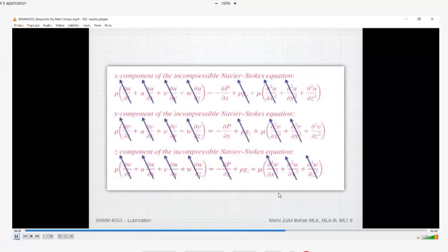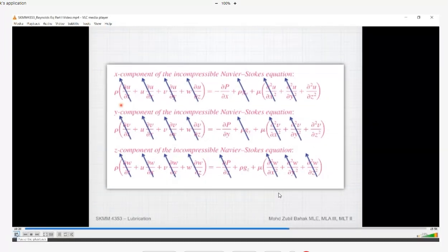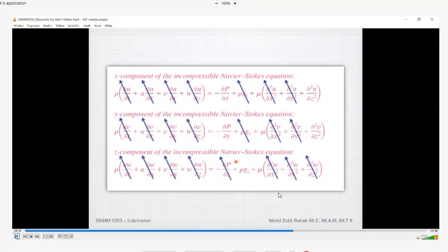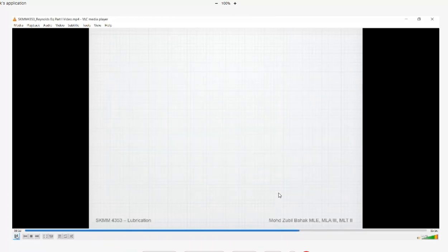When we take the Navier-Stokes equation with all the 8 assumptions that we have there, most parts of it will cancel, and also the rho g z term is cancelled because of assumption number one, that there is no weight being taken into consideration. Because of this cancellation, finally we have this.